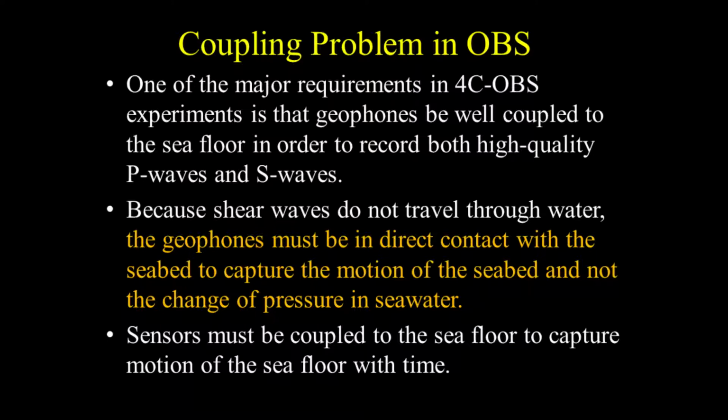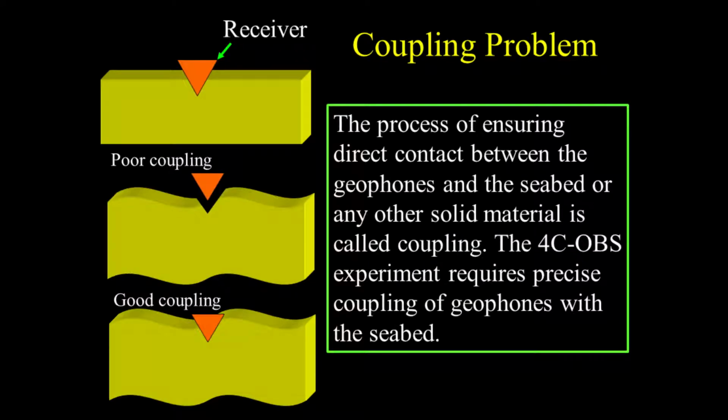Sensors must be coupled to the seafloor to capture motion of the seafloor with time. The process of ensuring direct contact between the geophones and the seabed or any other solid material is called coupling. The 4C OBS experiment requires precise coupling of geophones with the seabed.